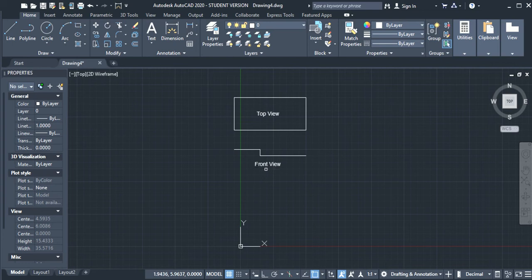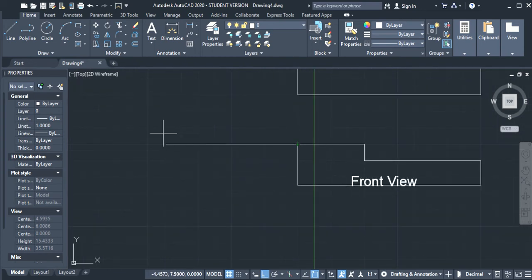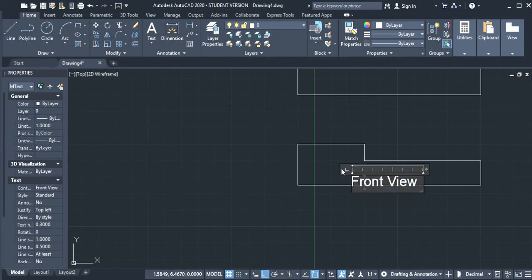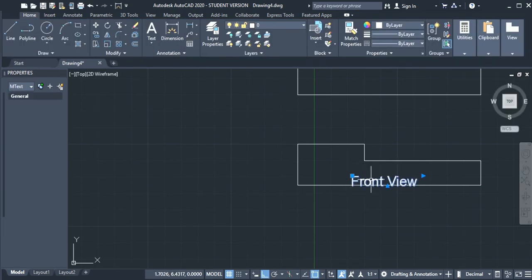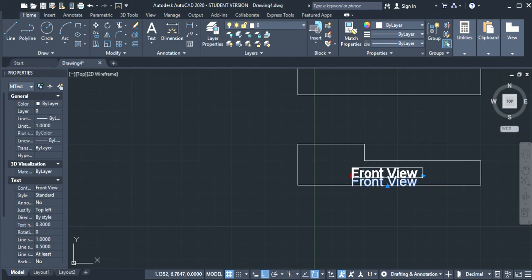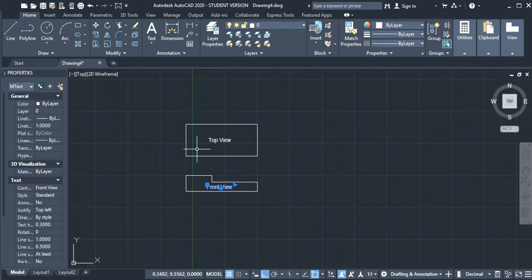There we go. And I'm going to come back through with an L, escape line tool. I'm going to click right here, turn on ortho. I'll go down. Actually, the distance down is 1.25 minus 0.5, so I actually know that distance to be 0.75. That's better. Now it's 5.5, and then I can go ahead and close. Escape to get out, right click, double click, and I can move it. That's better. Yeah, that looks more like the assignment.